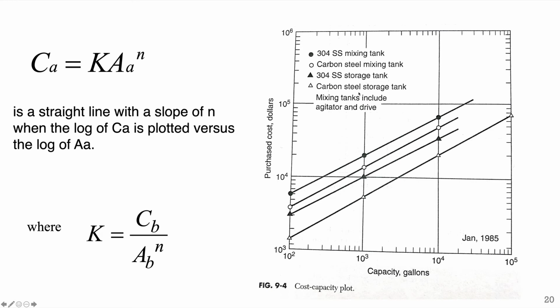So it's not only the type of tank or equipment, the right use, but also the materials of construction. Stainless steel may be good for operations where you have high temperatures, or when you have chemicals that are not compatible with carbon steel. However, it has a cost penalty, as shown here in this graph. And we're going to get into that, but I just want you to see it here.